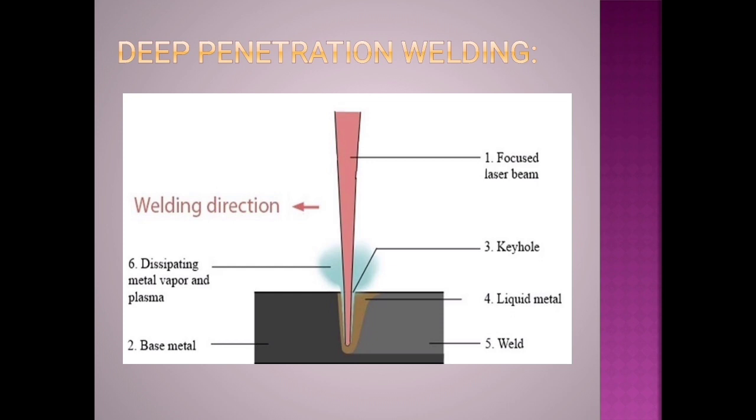So, there occurs an equilibrium stage between the pressure created in the hole and the molten bed. This determines the penetration depth when either the workpiece or the laser beam moves relative to each other. Molten metal flows behind the hole and gets solidified and the weld is created. Such a laser has a great depth to width ratio. This is called deep penetration effect or keyhole effect. And the results of high power welding is similar to that of electron beam welding.